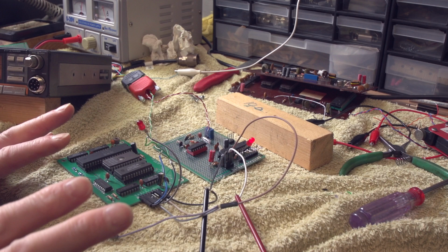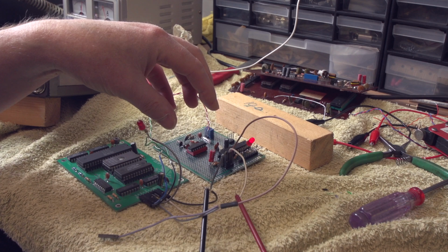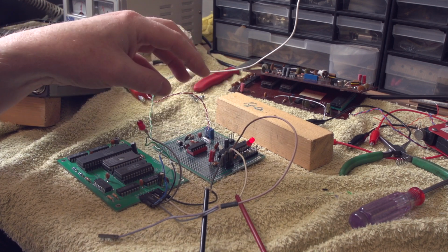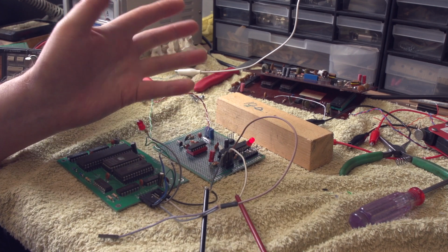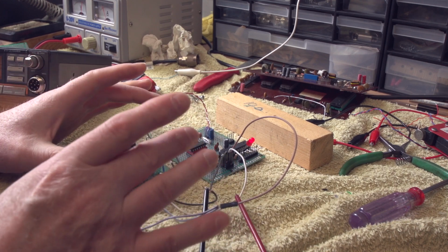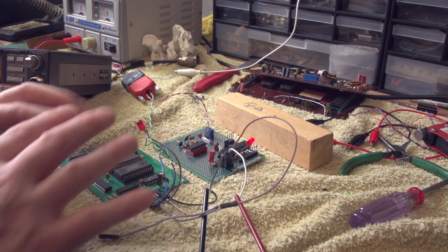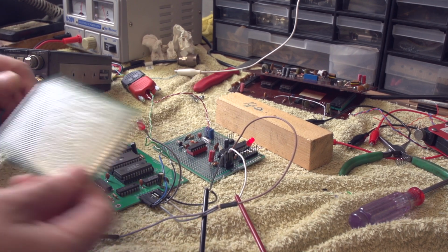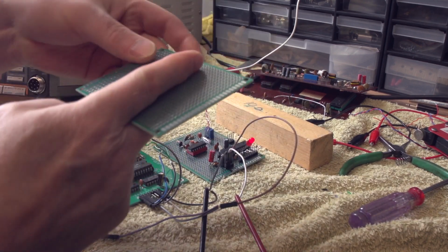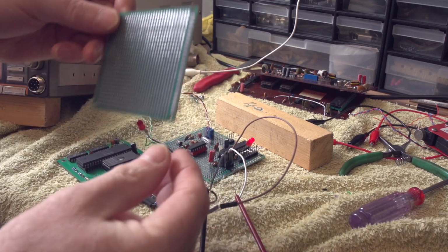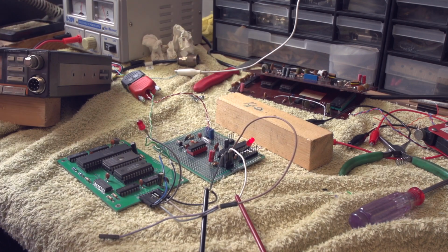The next thing we need to look at is expanding the card so we can handle something on the transmit side as well. That means we need to build a side-on oscillator at around 800 Hertz, between 700 and 800 Hertz, and we need to build some sort of switching to route the audio signals. So that needs to be handled, and what I'm probably going to do is just take another bit of this board and build it on there, and we'll stick this on here, and probably I might trim this down. It's too big really for what we need. And then maybe it's just soldered onto this card here and make it bigger.